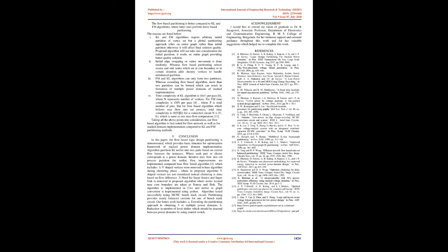3. FM and KL algorithms can only form 2 partitions, whereas by extending the flow-based algorithm, more than 2 partitions can be formed, which can result in the formation of multiple power domains of stacked implementation. 4. The time complexity of the KL algorithm is O(n^3) per pass, where n represents the number of vertices. For FM the time complexity is O(p) per pass, where p is the total number of pins.